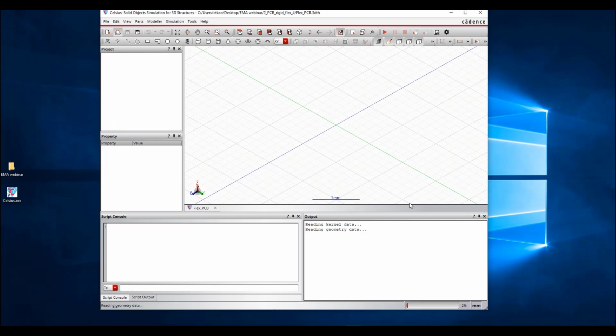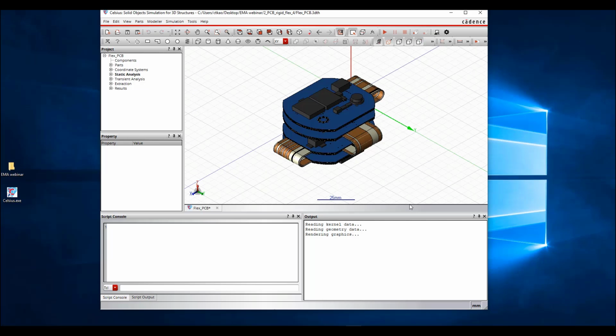It's also created by Allegro in step file, in true 3D solid modeling. Allegro can export step files and 3D models easily, and we have no problem reading in those step files. Remember, the first example we just showed was created from a SAT file. This one is created from a step file.